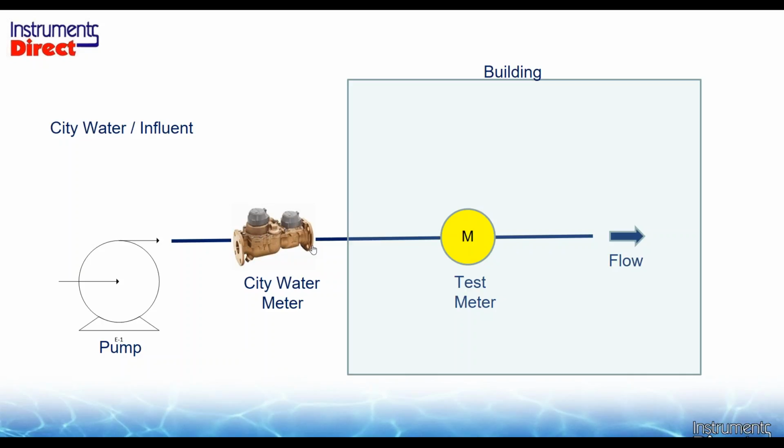So in some cases, the discovery process is limited if you have an exotic type of flow meter. You need to know the flow meter specification; sometimes you need to use the right piece of equipment for the application. If they did not have this city water meter that monitored the high flow and the low flow, guess what? Non-billable water would go through this meter because it wouldn't pick up the low flow.